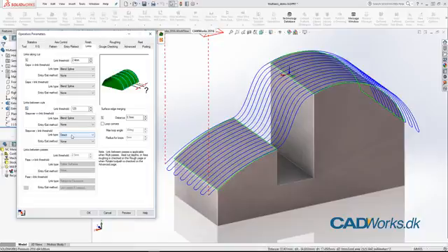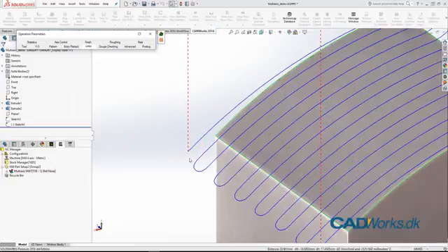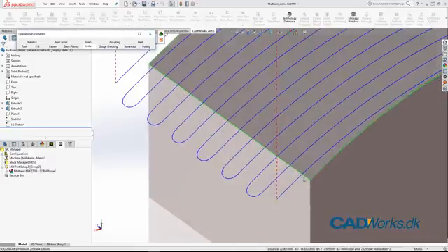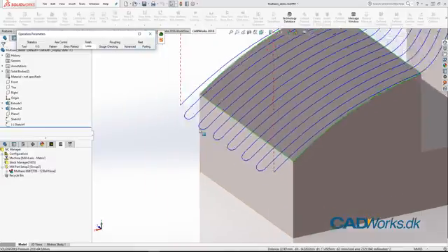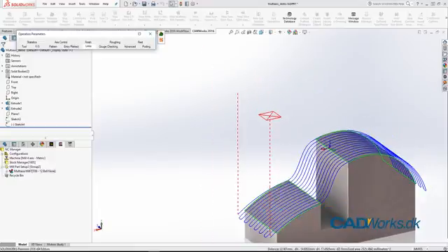Most of the time you would probably like to go for the same option in here. So blend spline. But you will see for yourself when you are starting to program parts how this is working best for you. So now we got the toolpath that we want, and it's looking really nice. Only thing is we come in at rapid and then we feed. Actually, we come in over here and go around because we have our entry point from that one.